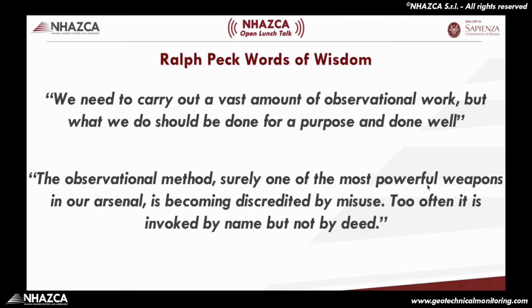Another word of wisdom is a little bit harder and relevant, especially today, I think, but also at that time. The observational method, surely one of the most powerful weapons in our arsenal, is becoming discredited by misuse. And this was happening, let's say, at the beginning of the observational method. Unfortunately, today this problem has not been reduced so much, so it's very important to keep this point in mind. Too often, the observational method is invoked by name, but not by deed.